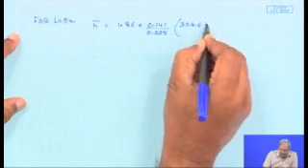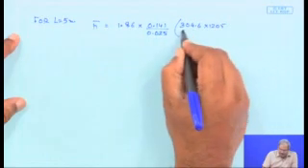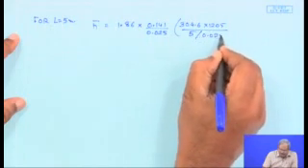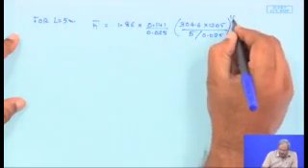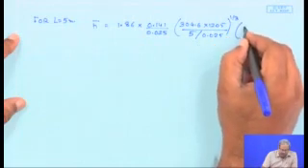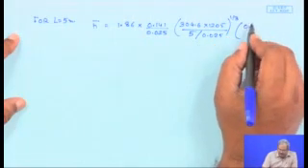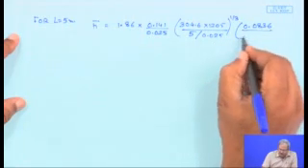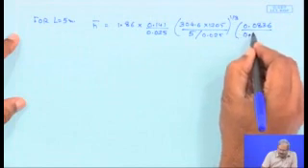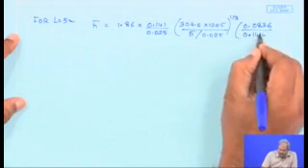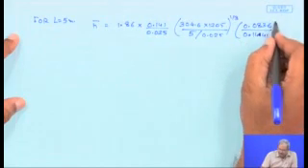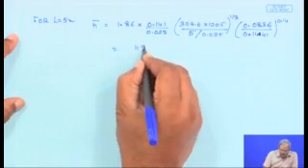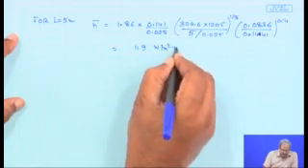Reynolds number, Prandtl number, the length of the tube divided by the diameter to the power 1/3, and mu by mu s. So, the viscosity based on the bulk temperature, which is 0.0836, and the viscosity at the temperature of the wall to the power 0.14, and you calculate this H to be 119 watt per meter square Kelvin.